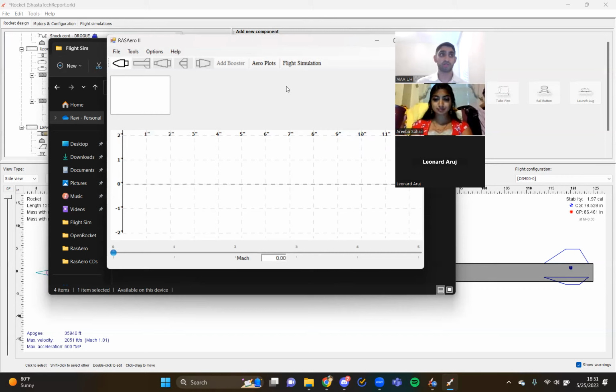So I think starting from like Oberon's first launch and maybe even Prometheus, but definitely with Oberon in 2021 when they conducted a test launch at the South site and their other launch at Texas Shootout, and for Zenith's launch at Spaceport in 2022. For all three of those flights, OpenRocket has overshot or overpredicted the apogee, and we've fallen usually well below what it predicts by a good few thousand feet.